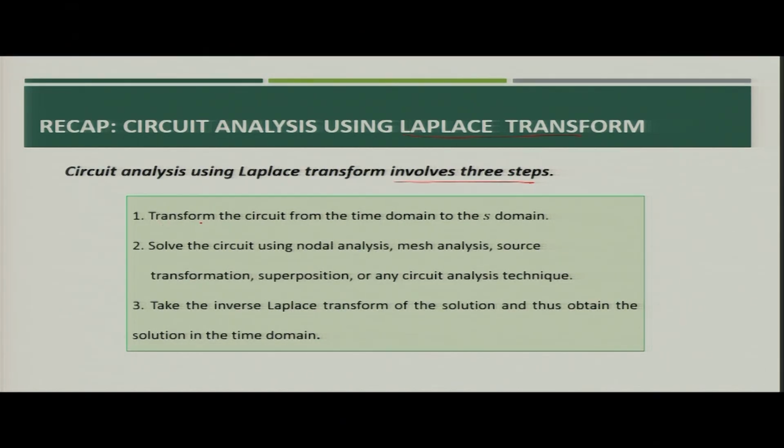First step was the transformation of the circuit from time domain into S domain, and then we solve the circuit using any circuit analysis technique, that may be nodal analysis or mesh analysis, source transformation, superposition, and so on. And then finally, the result we get is in S domain. So, we take the inverse Laplace transform to find the solution in time domain.